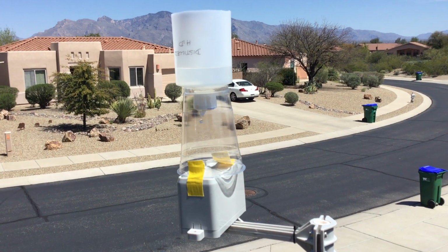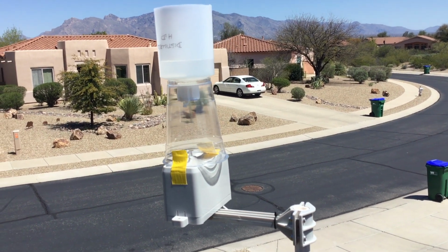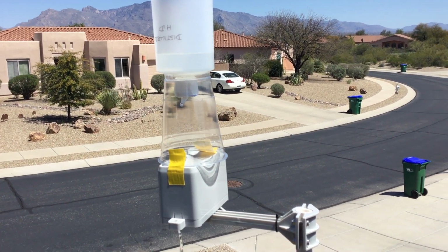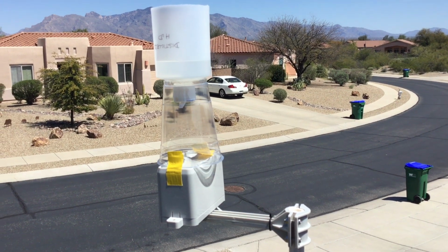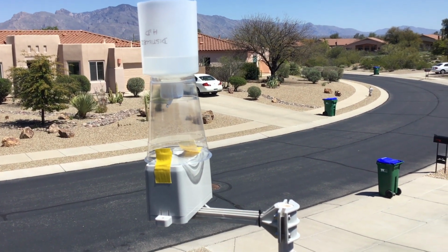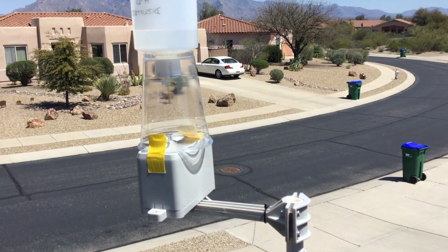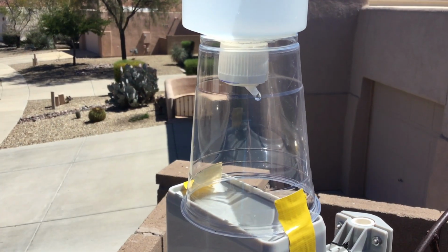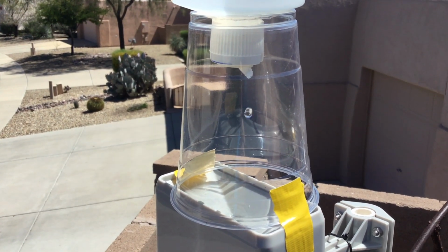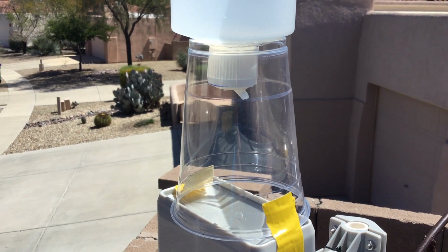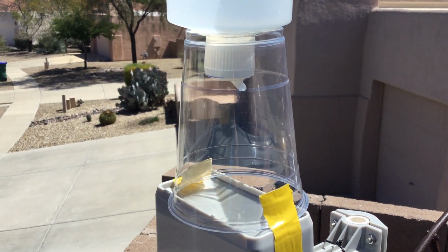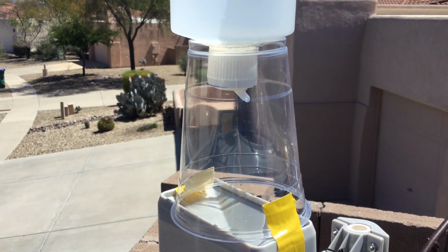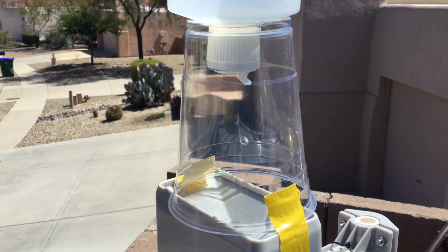All right, so this was a setup I developed to see if I could create something that would better approximate a rainfall event rather than me just pouring water into that gauge. So this is a little bit gentler in terms of engaging the bucket. I'm not overwhelming that bucket. It's tipping only when it has to, so I should get better results going about it this way.